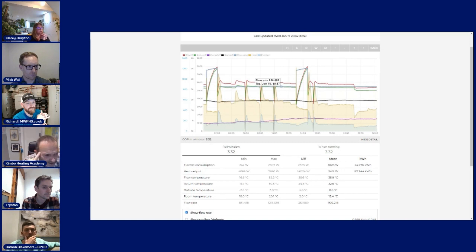Well, it seems the Vaillant runs a lot happier. The majority of the year they run closer to DT 2 and 3. What we were finding when setting these up, if you weren't going to go through summer and winter changing settings on them, was that when we set them up for DT 5 and ran them differently, it was struggling. Some of the rooms were struggling to get warm on the radiators, and they were balancing from the valves.